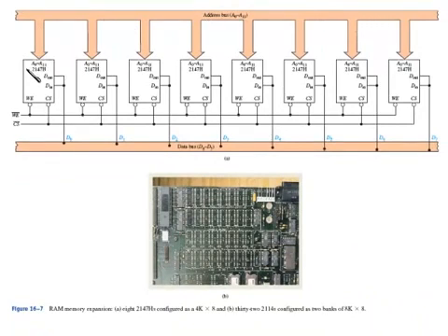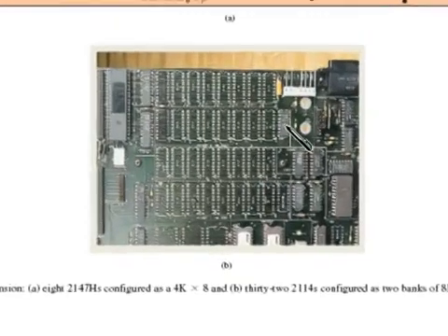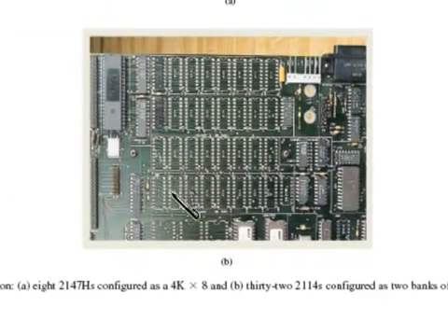So they're all active. One cell in each one of these is active at the same time, so it dumps a whole byte down onto the data bus. When you look at circuit boards, you'll see them populated with many single bit RAM chips to make up a full byte.